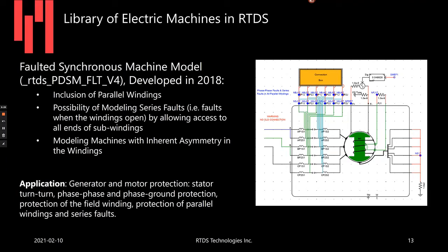An application is generator and motor protection, stator turn-to-turn, phase-to-phase, and phase-to-ground protection, protection of the field winding, and protection of parallel windings and series faults.